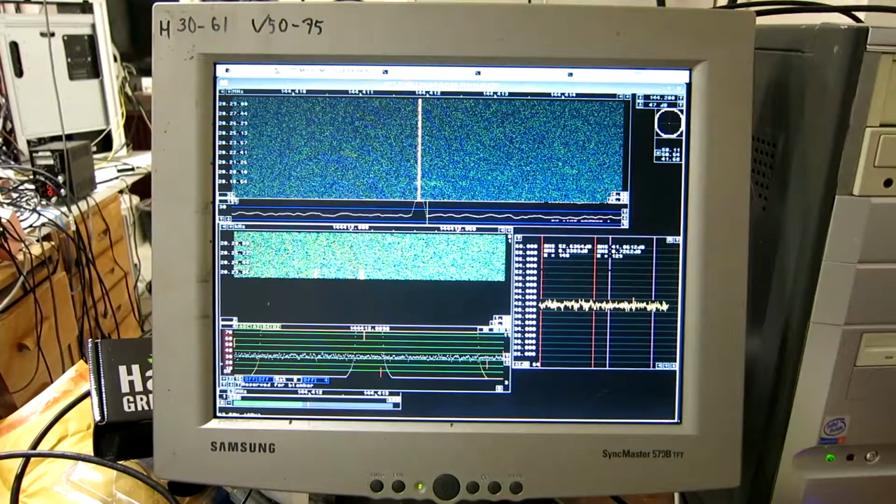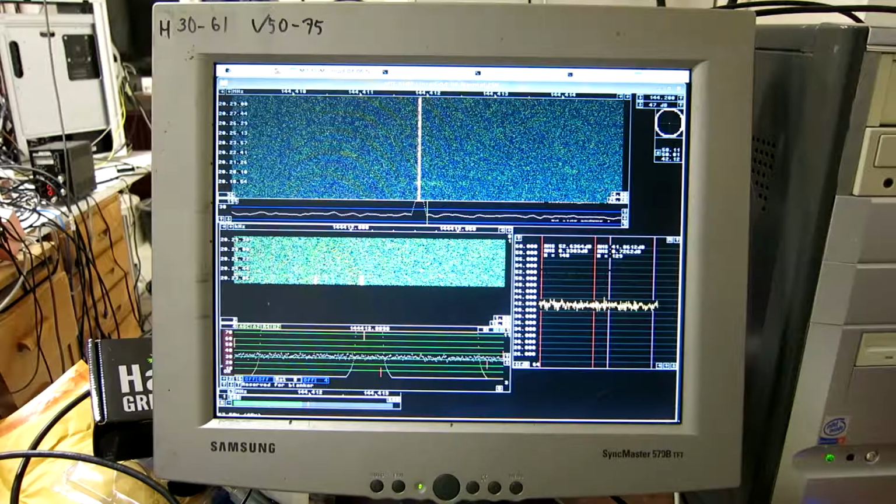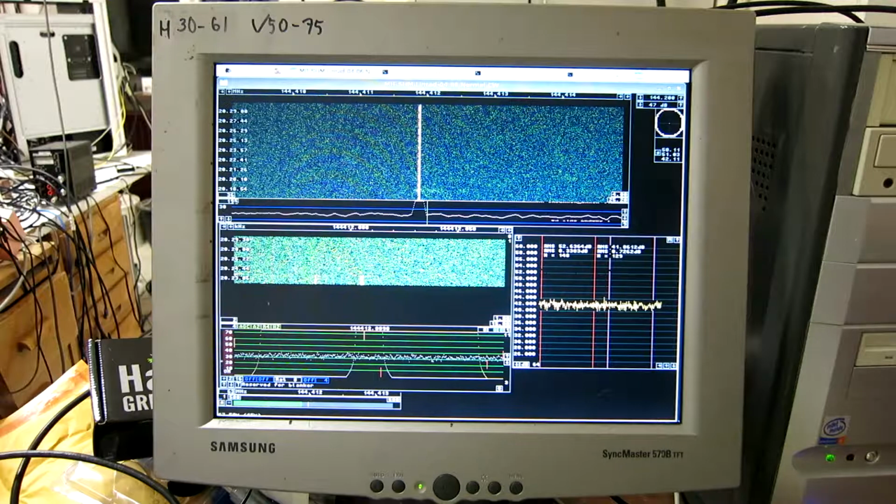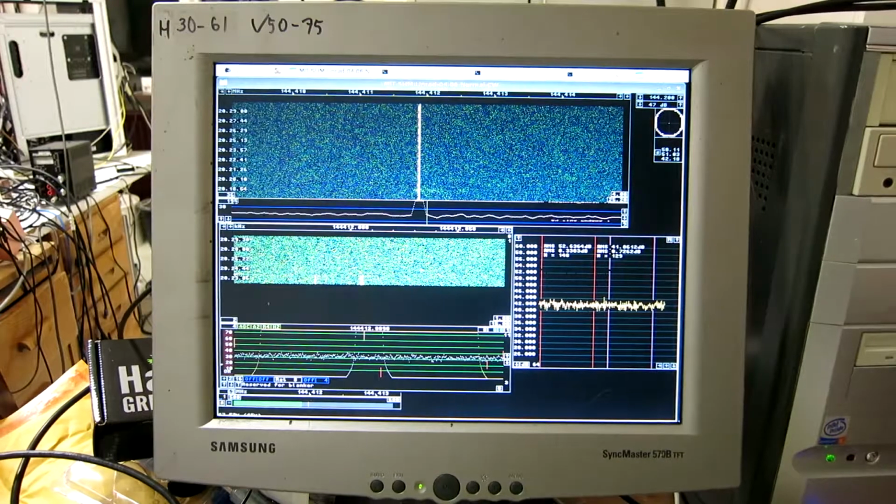The noise floor is very close to minus 174 dBm in 1 Hertz bandwidth, because the low noise amplifier has a noise figure of, I don't remember exactly, 0.15 decibels or something like that. It's practically zero with the accuracies we talk about here.